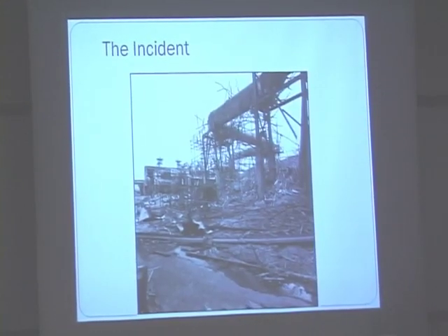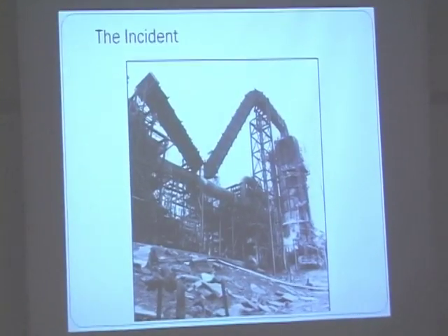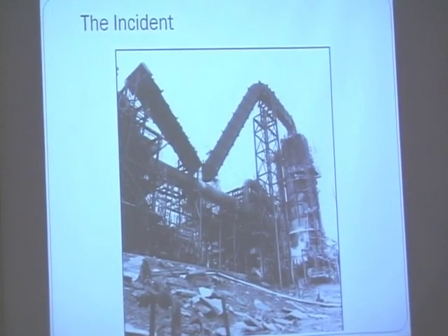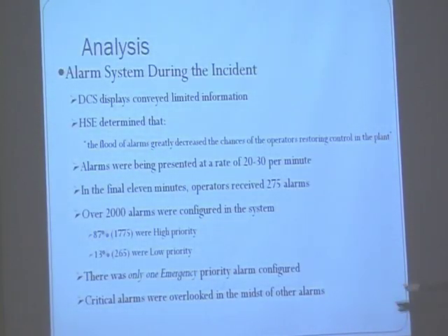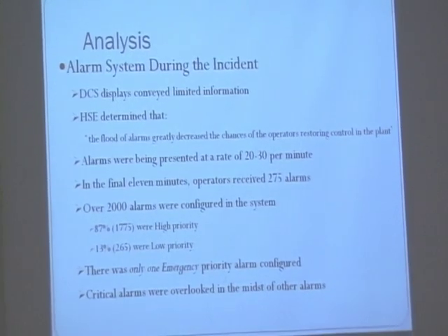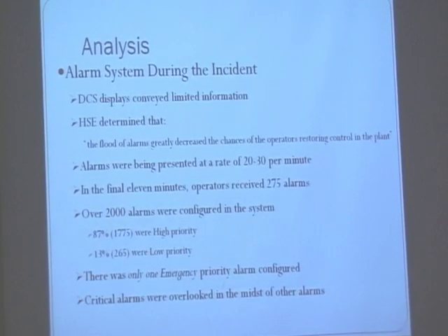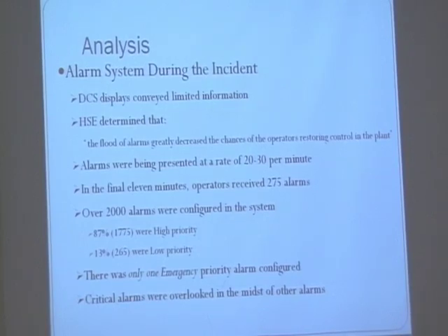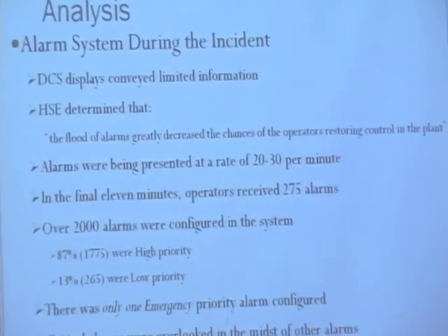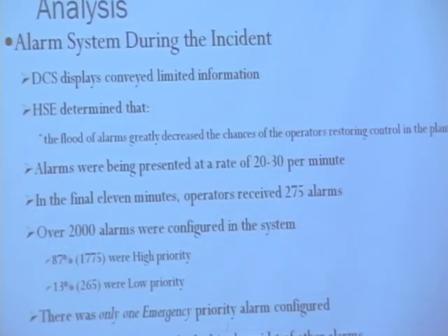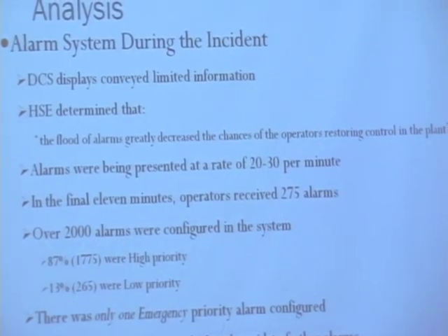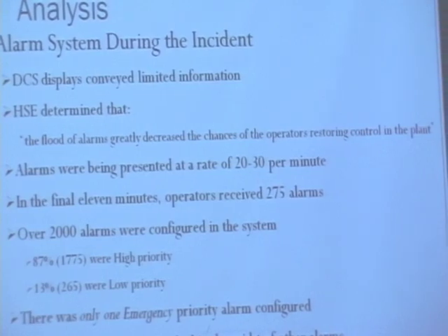Another picture of it. And again, Texaco's plant was down for 2 years, very costly. But in the analysis of this incident, they said the alarm system during the incident, the DCS display conveyed limited information. The Health and Safety Executive, which is equivalent to our OSHA, said that the flood of alarms greatly decreased the chances of the operator restoring control of the plant.